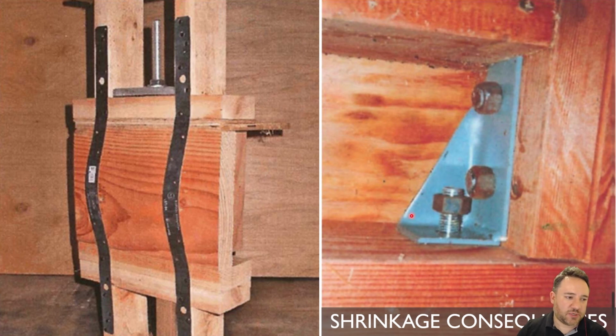On the right side, this represents what's probably a hold down bracket for a shear wall. So this is the shear wall chord here. Here's a bottom plate, and there's probably a few plates here, and then there's another wall below. And these brackets hold the whole thing together. Well, if these plates down here shrink in the cross-section dimension, and this time in the short cross-section dimension, now they've shrunk to the point that the bolt is no longer engaged here anymore. The things have shrunk, and the bolt, which used to be in contact on both the top and bottom, has now moved away because the wood has shrunk beneath it.